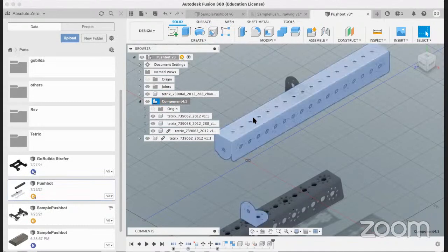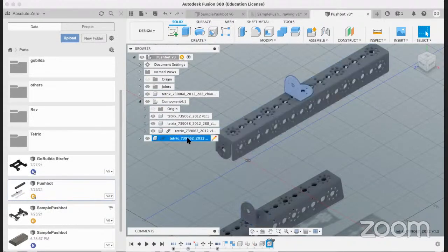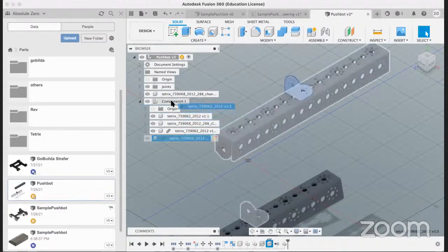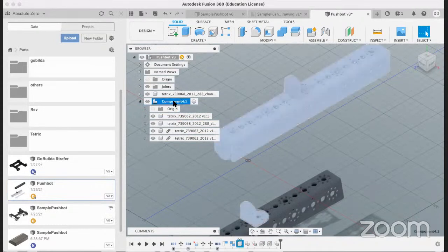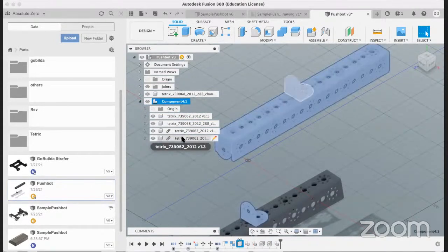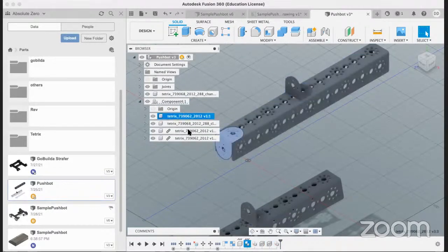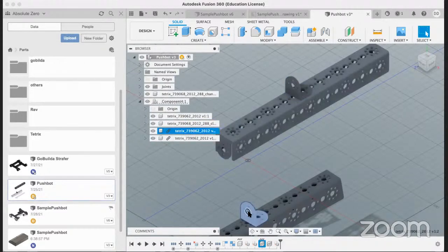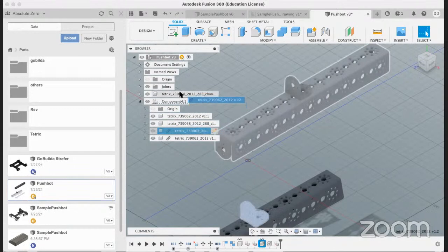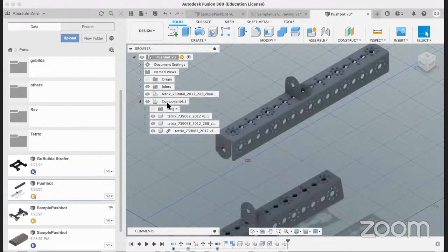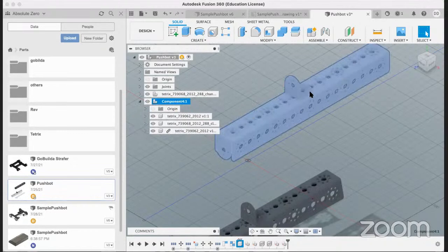So if I move this component, everything moves together, right? For example, this is also part of this component, so what I should be doing is moving it inside this component here. Okay, sorry, wrong place, I think. This one does not belong here, so I had to move it outside. Now this component has all these parts here. So that's how you compile them together as you build them, and then it becomes a lot easier to manage them. Okay.